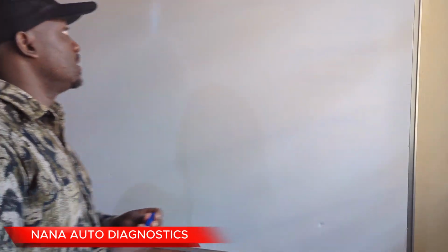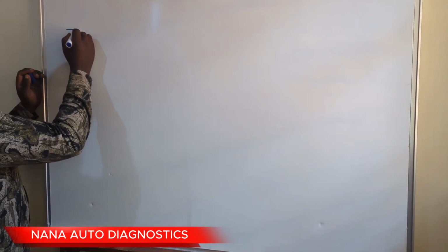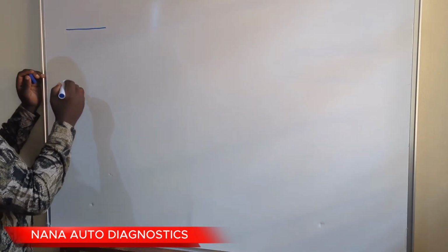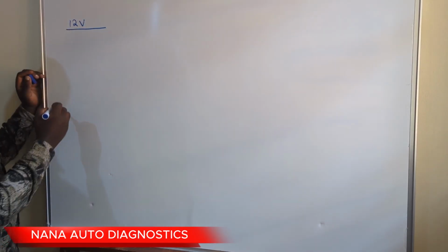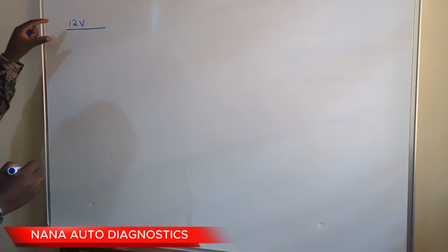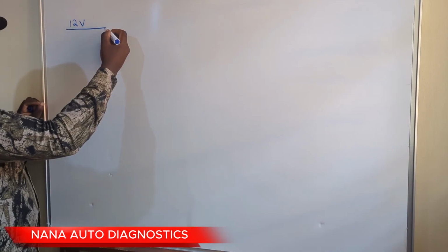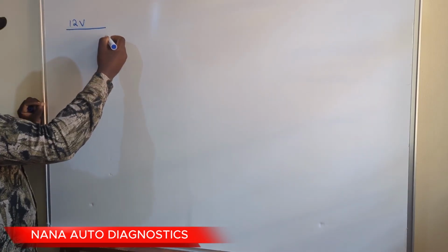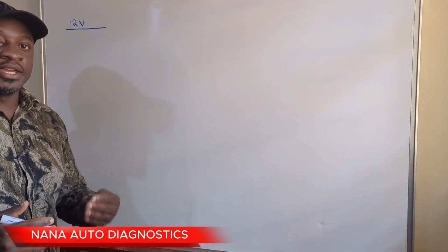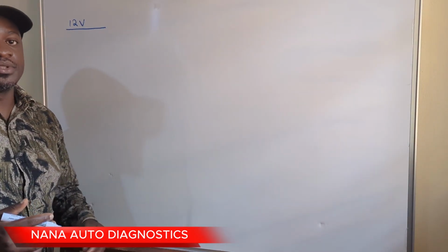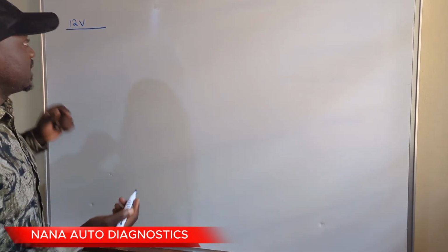What do I mean? Whenever we don't have any transmission on the bus, it will be at 12 volts, usually battery voltage. Whenever we attempt to have some bit of communication, this voltage will be pulled to about 0 volts. So let's go ahead and explain the various fields that are found in the message header.